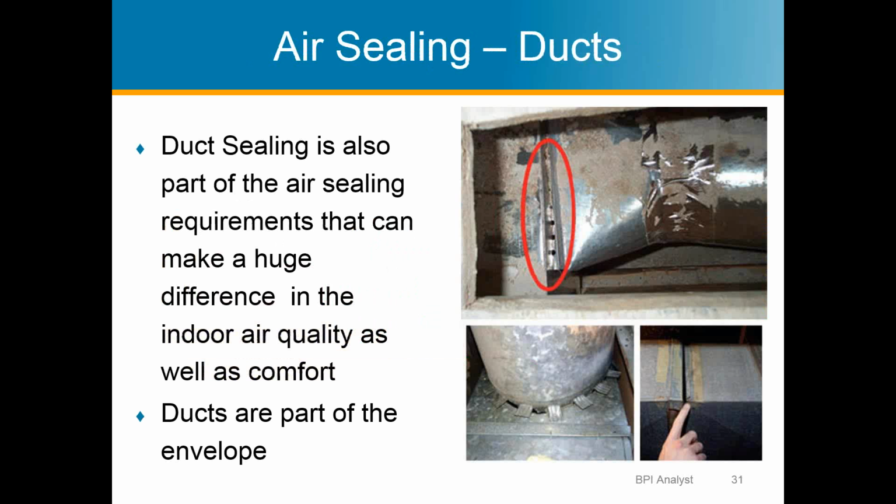And in ducts, again, ducts are so important for so many reasons to get sealed and have them done properly. Not only are you wasting energy. If your ducts are leaking 30%, then 30% of all the money you spend to heat or cool your house is wasted. Basically, it's a pretty direct comparison.